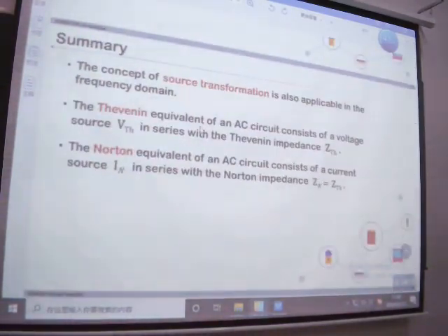And the concept of source transformation can be applied in the frequency domain. Just need to remember one thing: transfer the resistance to impedance and use Ohm's law for AC circuits. For AC circuits, we have U equal to IZ. For DC circuits, we have U equal to IR. Just remember, it's still Ohm's law, but in a different condition.